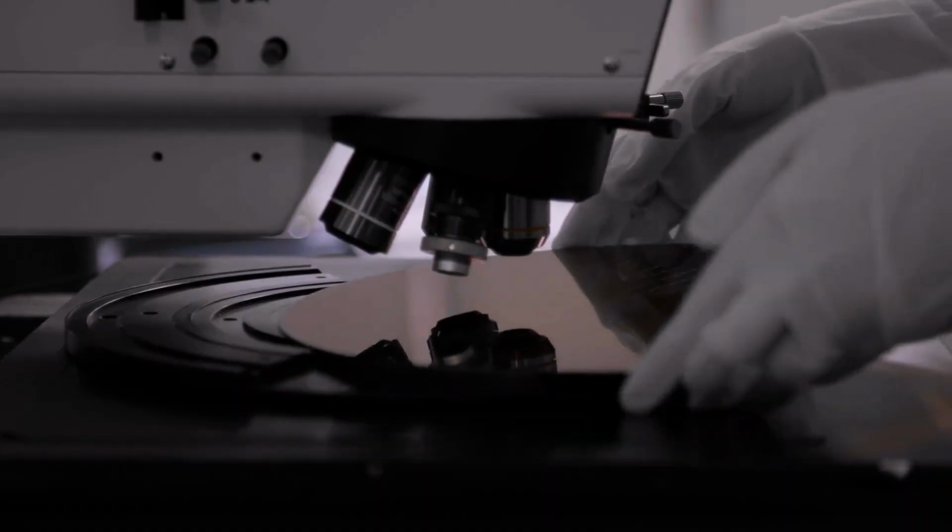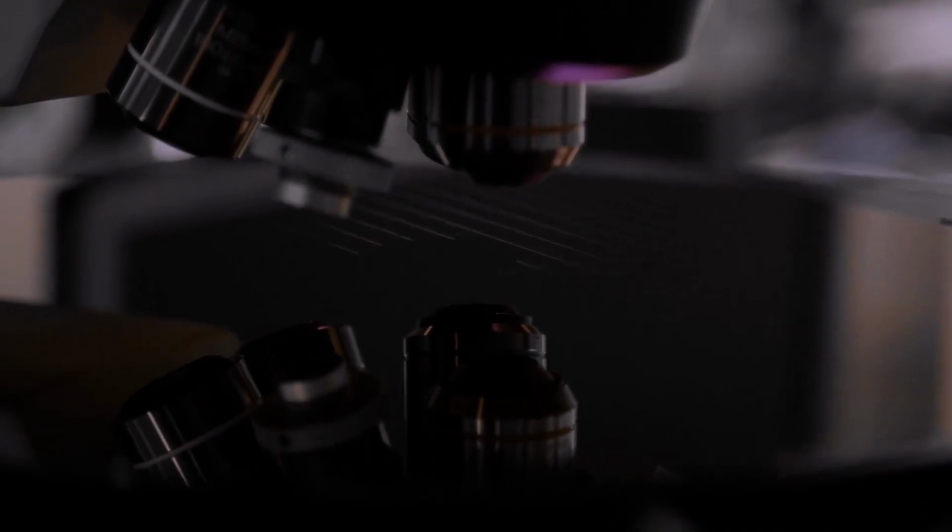So for ATM, we will receive the Foveros die, and we will do assembly, which is die attach or chip attach of the Foveros die on the substrate and the packages. We stack all the die onto the wafer, and then take it through the flow. We then singulate or chop up that particular die into what we call the die stacks or the Foveros stacks.